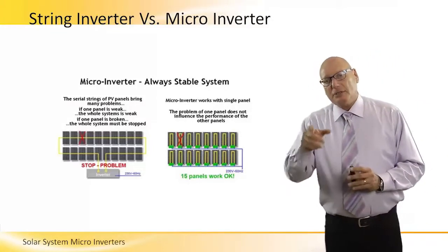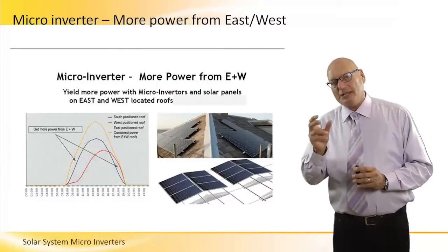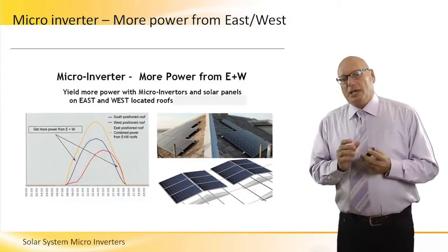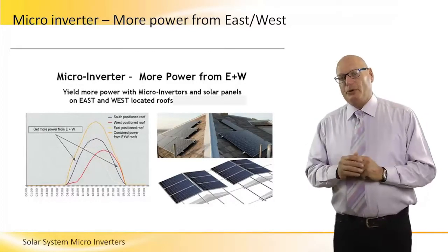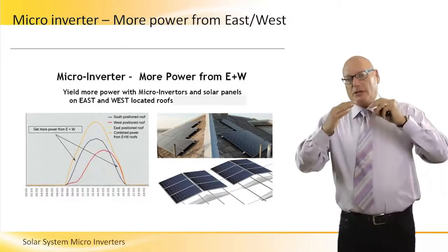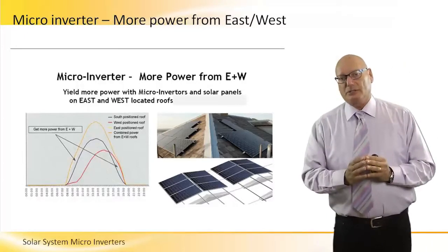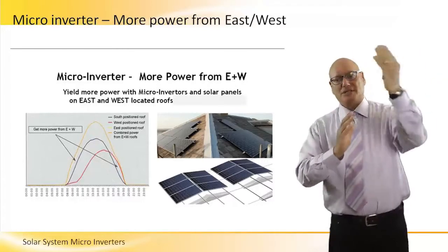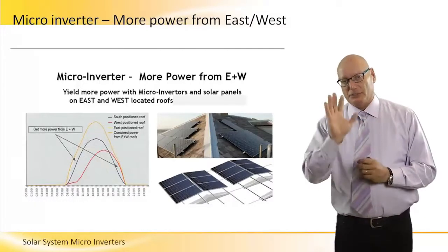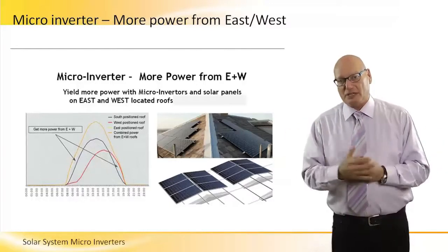Now, because the microinverter uses an MPPT circuitry mechanism, it keeps the IV, like we said, at its maximum point. That allows locating and installing panels not only south-facing, where the sun is moving and the sunbeams directly hit the surface. We can mount panels on the east-west side.